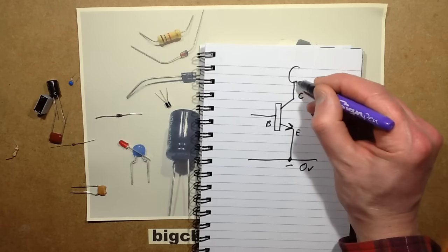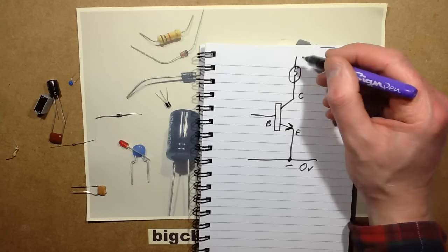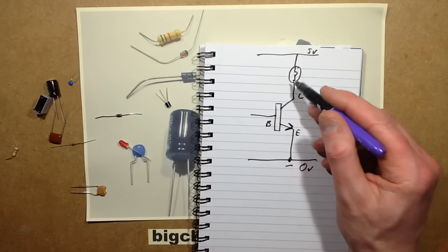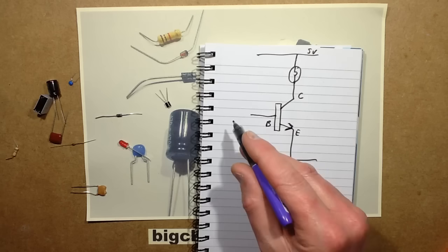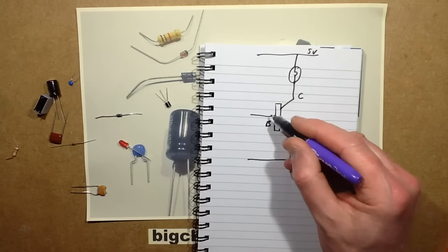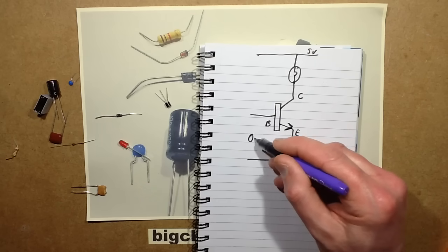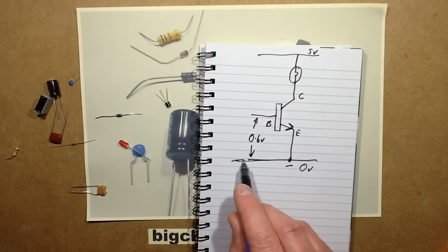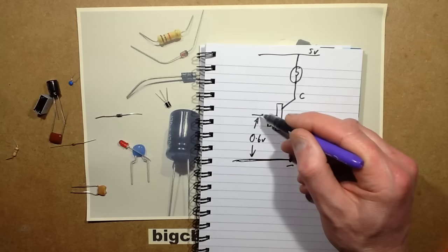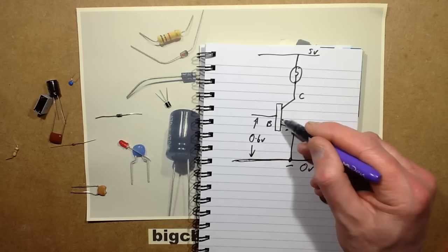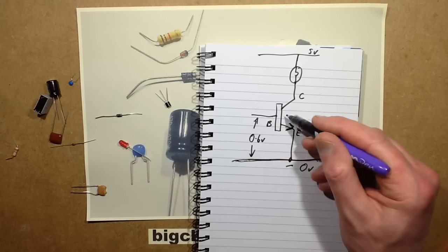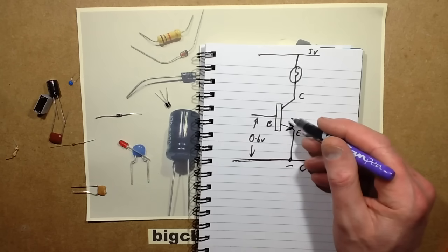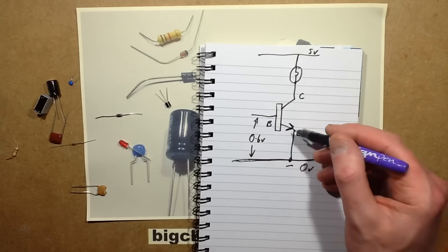Supposing, for instance, you had a small tungsten lamp, and you had, say, a 5 volt supply. If you wanted to turn the lamp on and off, but you only had very limited current available, you can use a transistor. As soon as you exceed about 0.6 volts, because it's silicon again, that's the standard silicon junction voltage, above the ground rail, the 0 volts, and a modest current. A transistor typically has a value called a gain. It's got a voltage rating, a gain rating, and a power dissipation rating. There are lots of other ratings, but let's keep it simple, because in most instances when you're using a transistor, it's going to be an NPN like this.